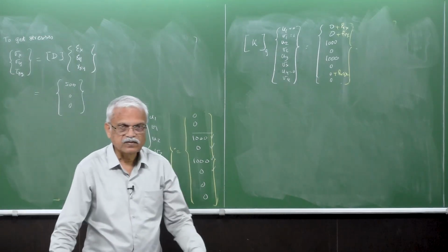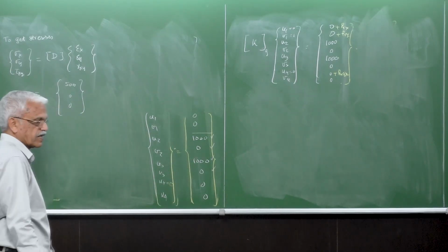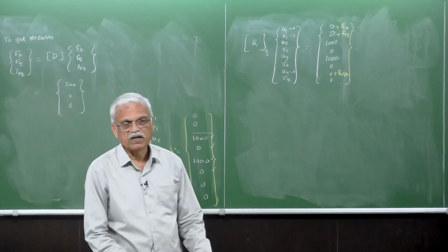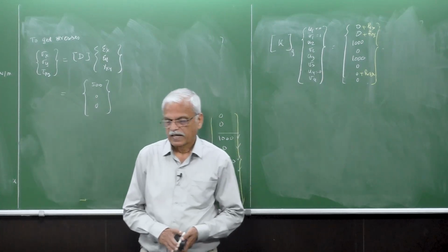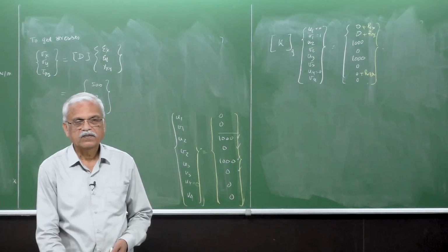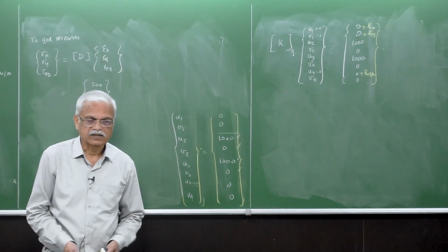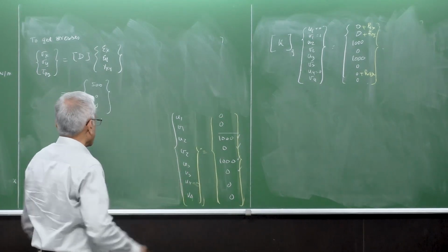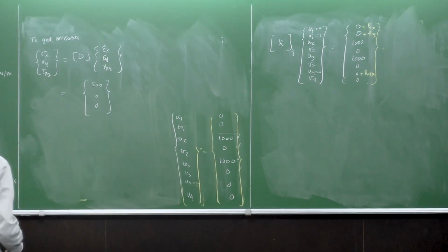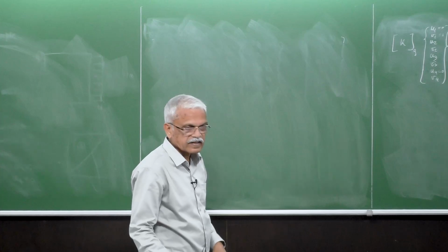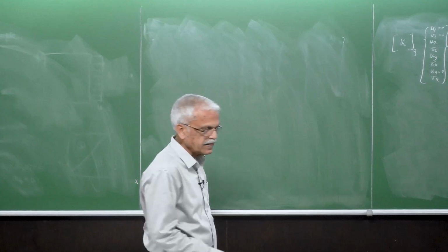Okay. So I hope, after getting these displacements, we have extracted the nodal displacements for element 1, and then we pre-multiplied with B to get the strains, and then with D to get the stresses. So this is how we can solve the problem completely. This is a simple problem, but I went through all the steps to illustrate all the major issues. This analysis of 2D can be extended to 3D very easily.